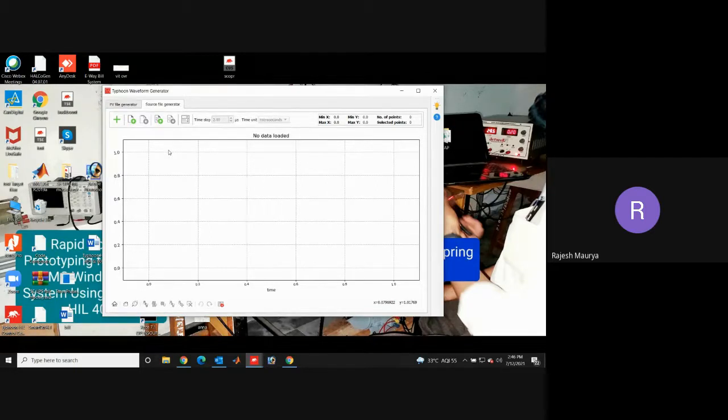that file can be used in a schematic. I'll show you when I develop the model for the MPPT boost charger, that if you have any .ipvx file, where and how to load that file. I'll provide you the detailed steps on how to do that. In MATLAB, we just provide this VOC, ISC data, we directly drag a PV panel, and we provide the data over there directly.